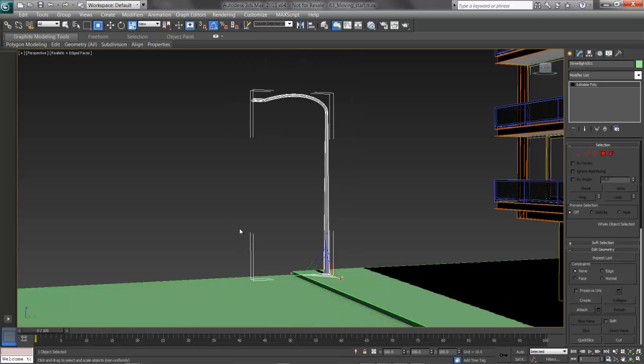In our scale then, we've got some different ways to work. Right now, I'm using Select Non-Uniform Scale, the middle option, letting me scale on one axis at a time if I'd like. There's Uniform Scale up at the top, which lets me scale the whole object on all three axes, as you can see highlighted here. Down at the bottom in the X, Y, and Z fields, I can read the percentage I'm scaling.